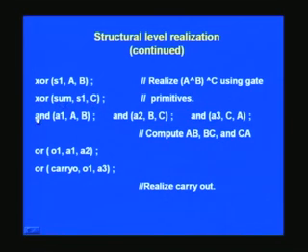And similarly you can AND A, B, B, C, C, A, and OR A1 and A2 here, right, assign it to an intermediate signal here, and once again you can continue ORing this with A3 which we have not used earlier. So thus we have got carry out as well as sum here.